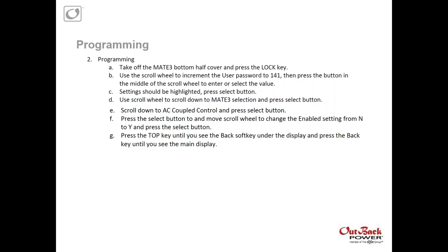Now, another thing to think about, whenever you're AC coupling, you're going through our charger rather than our charge controller. An AC charger is not going to control the charging of the batteries as perfectly as a charge controller would.